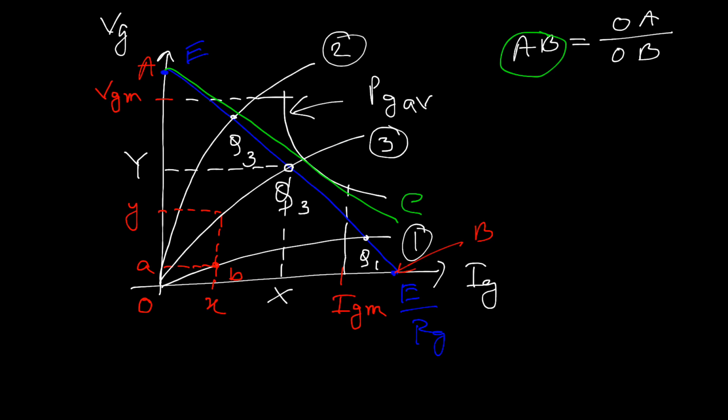It must also be ensured that the gate pulse width is sufficient to allow the anode current to reach and overcome the latching current, IL.